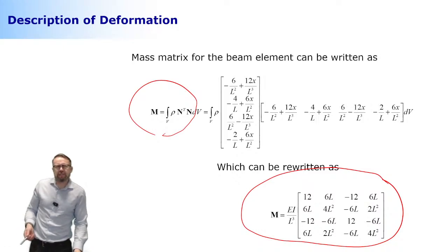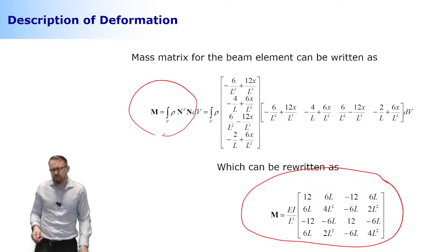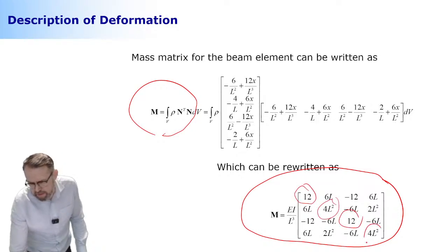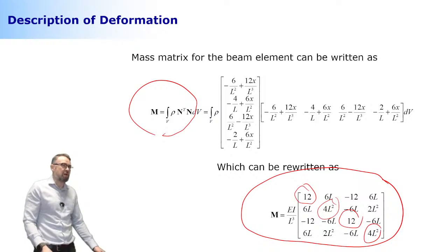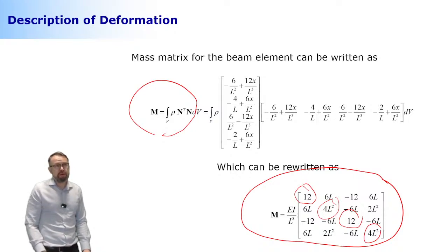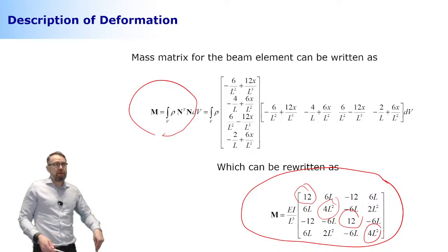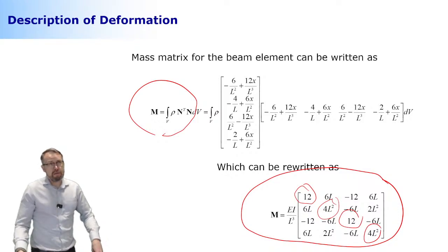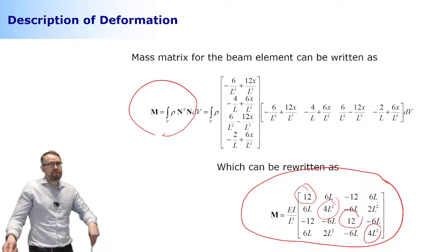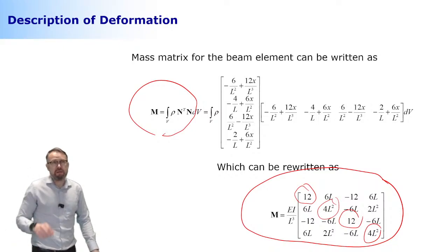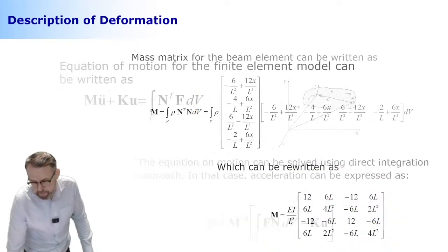But sometimes the technique used is that the matrix only consists of diagonal components, called the lumped mass matrix. And then there's a combination of these two. I don't even remember the names of these, but you can have 1/3 based on lumped and 2/3 based on consistent, and so on and so forth. This kind of combination exists in finite element literature.